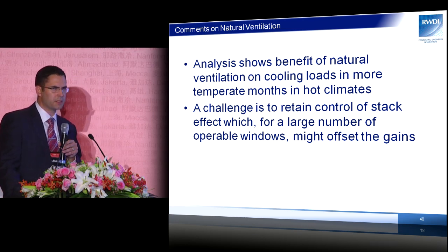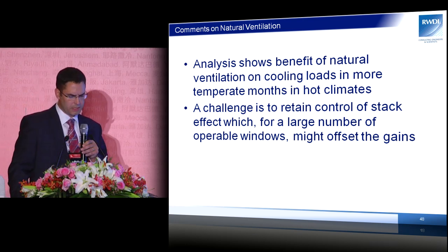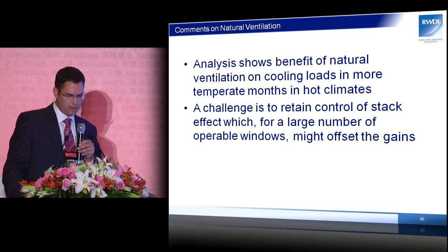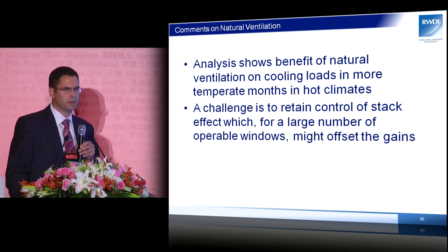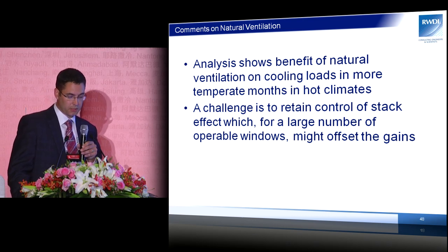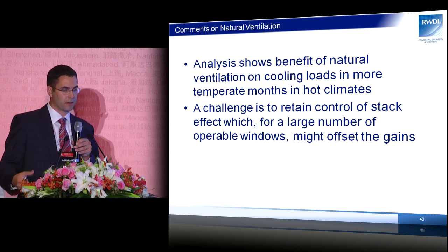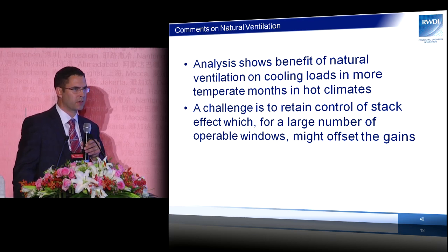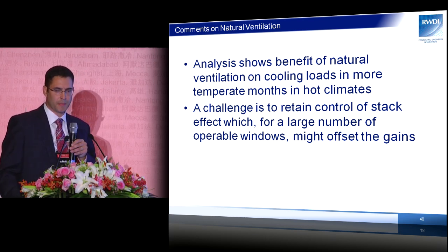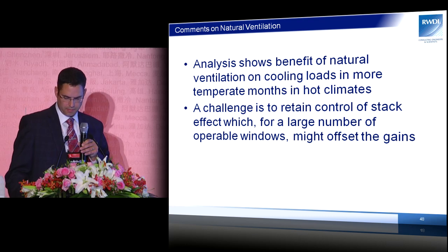But one thing that he's starting to explore in a little bit more detail is how to retain control of stack effect when you have operable windows in a tall building. Because if you introduce opening windows into a tall building, and of course the human factor, then one quickly overcomes any of the gains that one gets from natural ventilation because of stack effect.